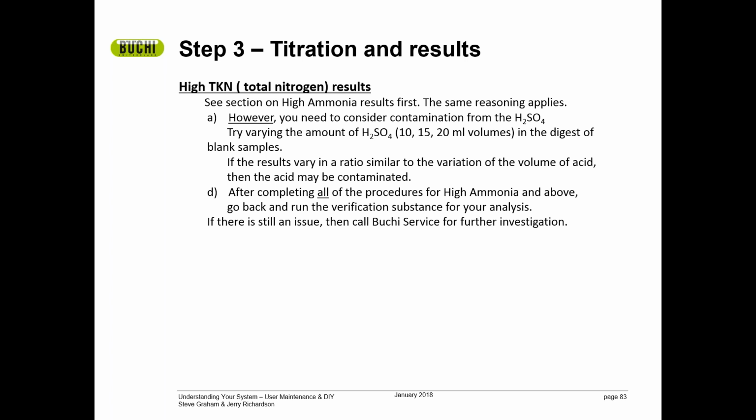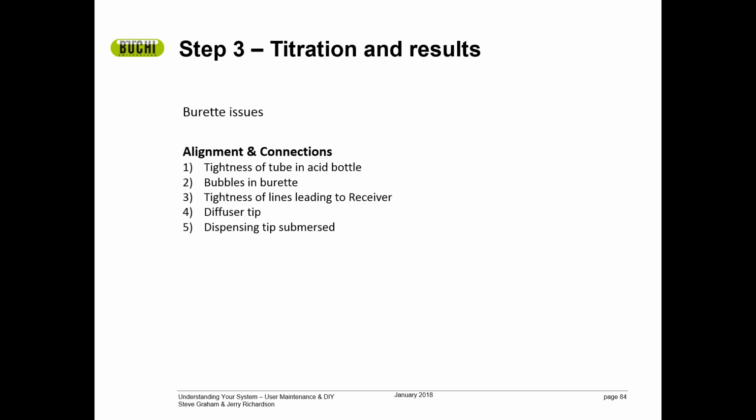Again, after completing all the procedures above, if you still have a problem with high TKN, please give us a call and we will certainly help you. There can be burette issues on the titration end of things. The typical issue is bubbles in the burette.